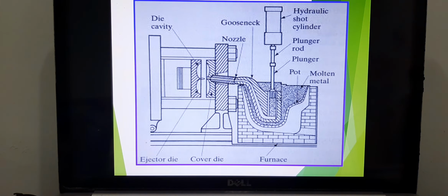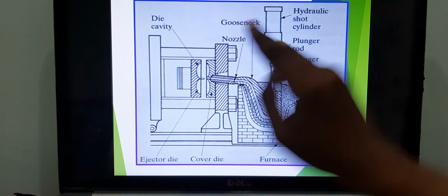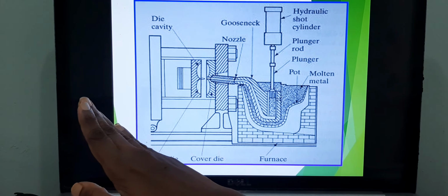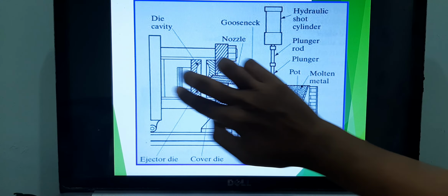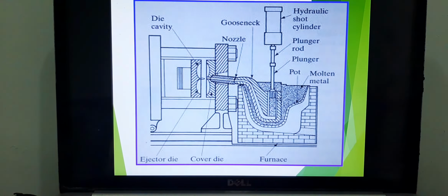So, for example, if it takes 25 minutes for it to solidify, exactly at the 25th minute, the moment solidification is complete, release pressure, the movable half of the mold opens up, the ejector pins will eject the casting, and the casting will be dropped off. Okay, the casting will cool down in room temperature. Then it's ready for the next round or next part.